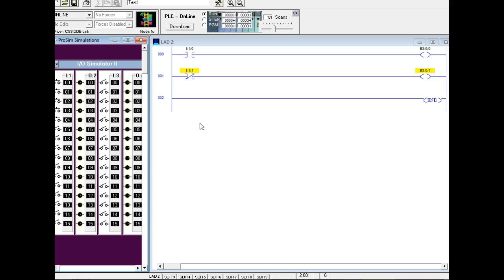So on the ladder, it will be the reverse of the PLC. Yes. If you use a normally open switch, well, what's the problem? So what I'm going to do is change this to a normally closed switch. This is set to examine if closed. So now it's true. It's closed, right? You understand? Over here it's true if it's open, right? You understand? Yes or no?